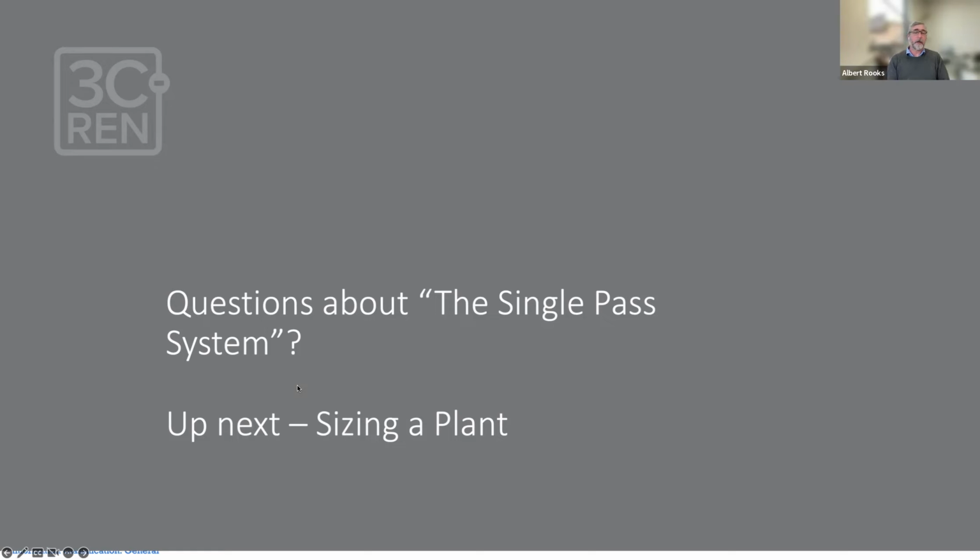But we've actually got to size the heat pump capacity based on what the manufacturer's specification for duty cycle is. And so you can undersize a building, and that means that the heat pumps would run longer than the duty cycle. And we want to avoid that, because we're outside of manufacturer specifications. The heat pumps are going to fail earlier, and some of the heat pumps are pretty big and expensive and hard to fix.